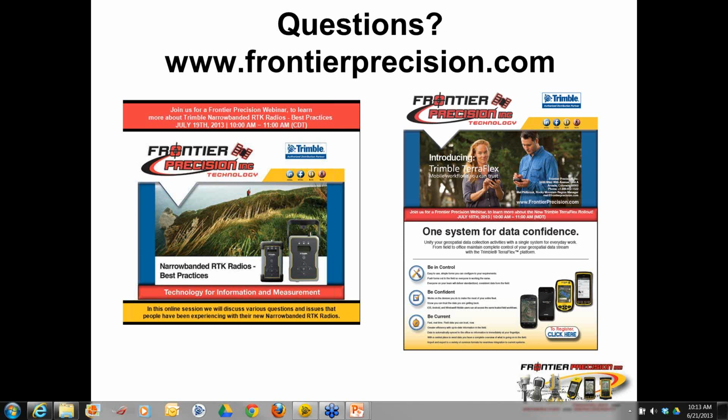That's a very good question. I would say to try to keep it under 5 megabytes for a TSC3. You may be able to go larger, but keep in mind that if you do, you're going to have some lag time in the map screen. When you try to pan or zoom in and out, it'll still work to an extent, it'll just be kind of choppy and slow. You might get to a point where if the image is too large, it'll just crash altogether.